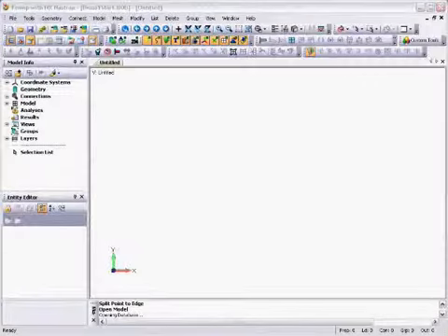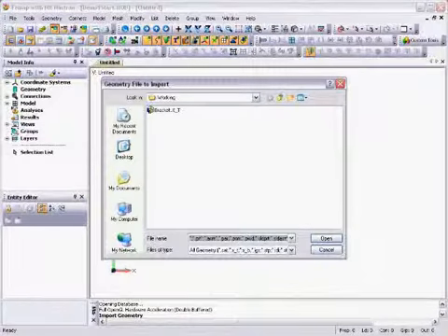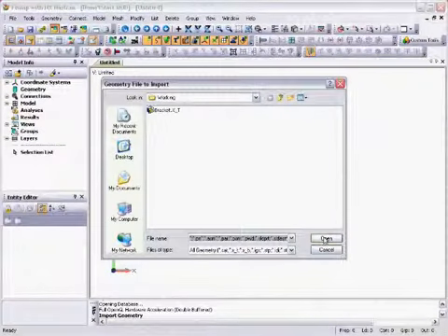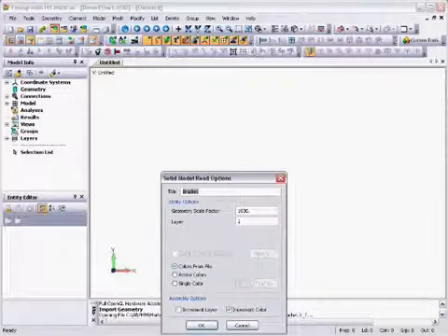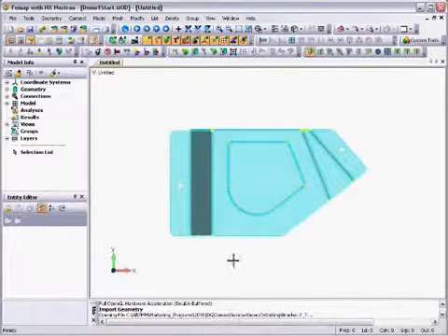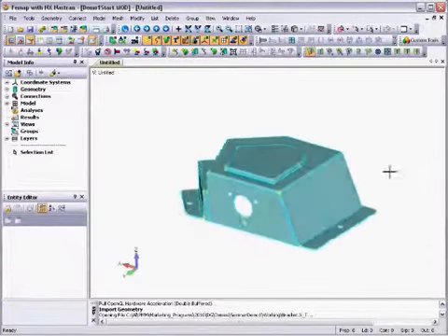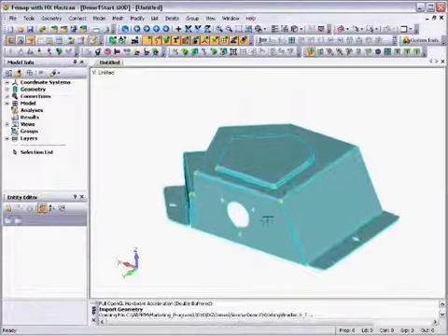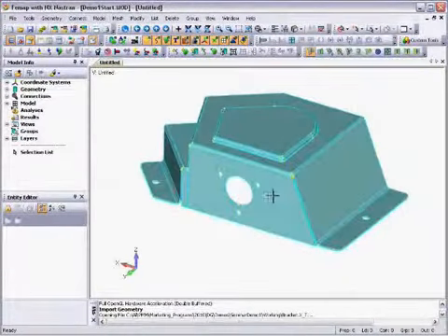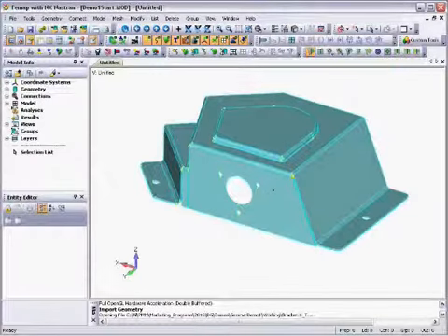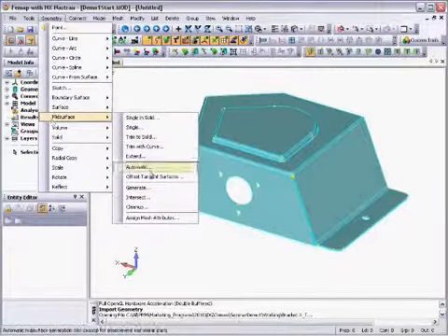The CAD model provides a convenient starting point for finite element model creation, so it's important to be able to access this data easily and robustly. FEMAP is CAD neutral and can provide seamless geometry access to all major CAD systems, including CATIA and Pro Engineer. FEMAP is based on the industry standard Parasolid geometry engine, and also supports all of the main geometry formats for import and export. With the geometry of the bracket model now imported, we can see that it's a thin-walled solid.